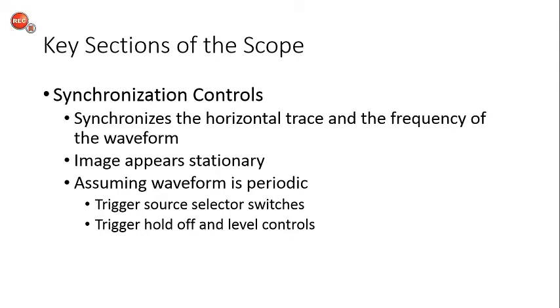And so if it's not a periodic waveform that we're trying to view, we'll capture one period of the waveform. There may only be one period, and then that will be remembered and repeated over and over on the screen for us.